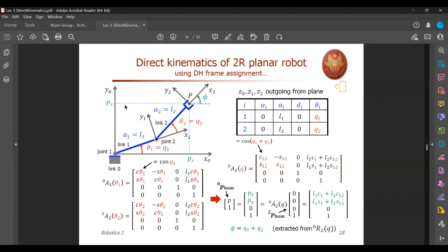First, we sketch the manipulator and identify the reference frame, x0, y0. And we don't have a world coordinate frame here. And we have the end effector here, which is actually the endpoint of link 2. So therefore, we don't have an additional end effector here, and the last transformation from the end of the last link to the end effector is also not there.